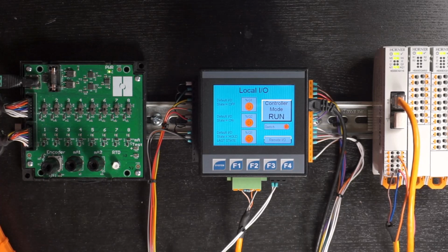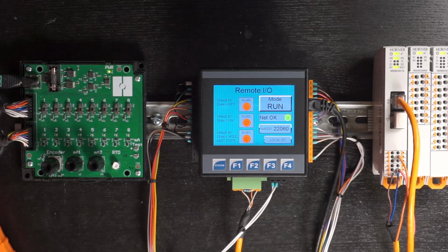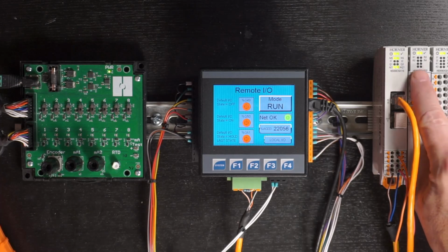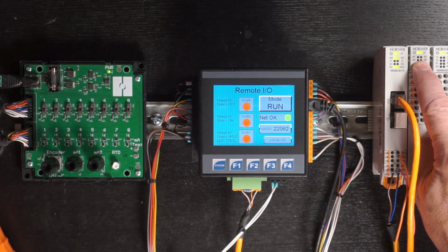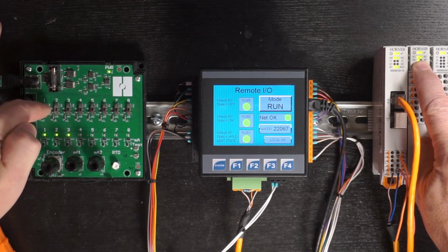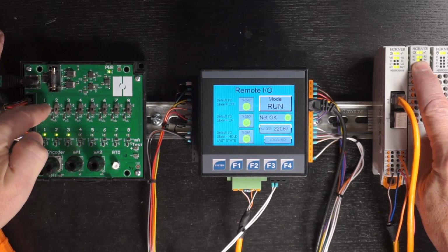Okay, now let's take a look at what's happening on the remote I/O. So I'm going to switch screens here. All right, and here's what I've got happening. First of all, we can turn our attention to these LED indicators here above my right index finger. Those are for the first 3 relay outputs on this card that I have adjusted the default I/O state for. All right, so I've configured it the same as what I did the built-in I/O. All right, so these follow the switch. Okay, so all 3 LED indicators are on over my right index finger. They're off, they're on, they're off.